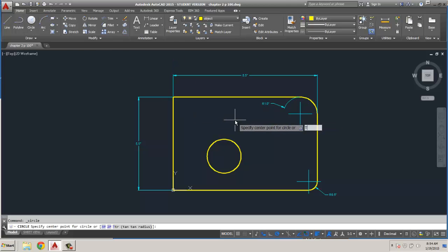Hit the circle tool, TK, enter. Left click, go over 1.5, enter. Down 1.5, enter. There's my point. Just hit enter again, and this one's going to be a 0.5 radius. Okay, so you may want to practice with that a little bit, just because it's kind of tricky in the mode. So just doing like a 2-point offset from a known point to locate these pieces.